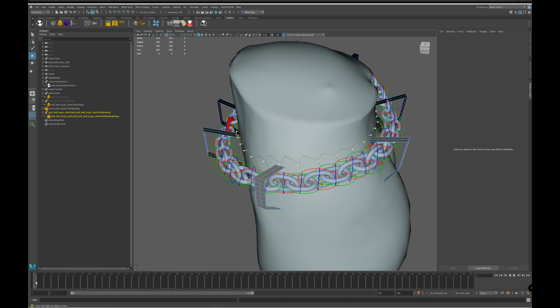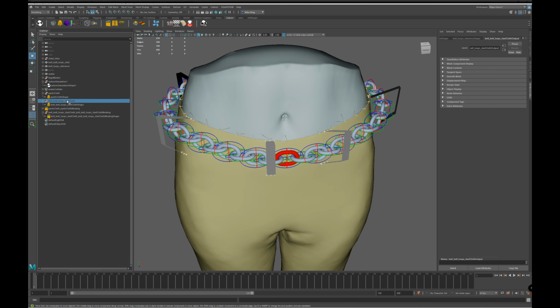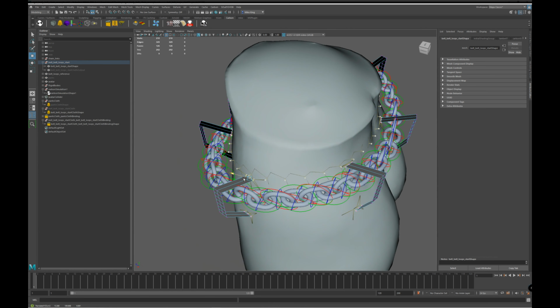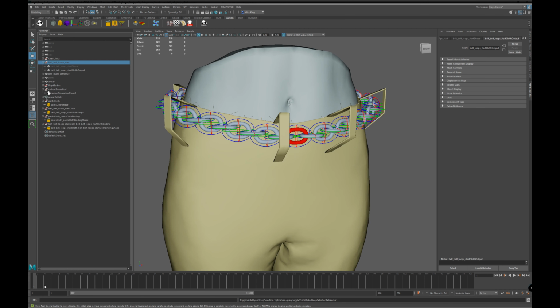So to be safe, let's just fix that. All we need to do is to grab those belt loop end vertices and pull them out of the pants. Okay, looks like I made a basic error and edited the geometry output mesh position. You can see that here. Maya takes output mesh edits as additive. So to fix this, I need to edit the input mesh and then re-add the belt loop start mesh to the cloth, and re-add the reference mesh and reset the simulation.